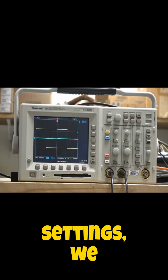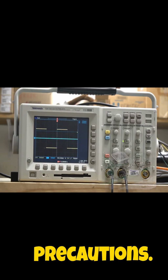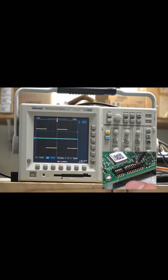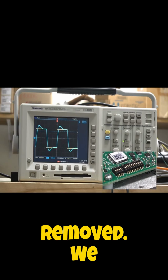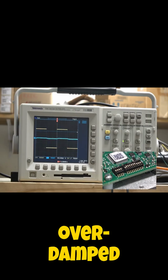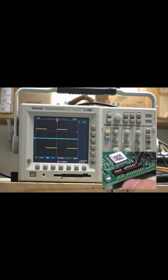Before we change the switch settings, we must turn the power off. This is for safety precautions. We just turned switch 7 on. Now we see that the overshoot has been reduced, but not removed. We are aiming for a smooth, over-damped step response. Let's turn switch 8 on now.